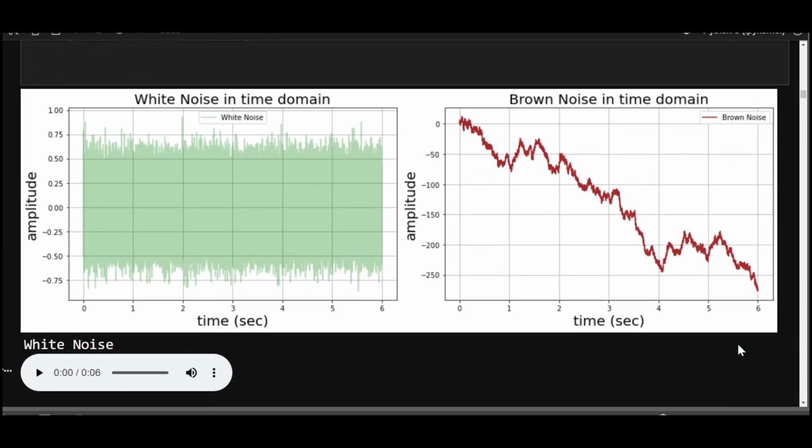So this is exactly how the brown noise looks. This was the white noise, and we just took it and integrated it. So you see here it's fluctuating so randomly. It has some very high frequency components. But when we integrate it, those randomly wild swings of this signal get low pass filtered. And as a result, you see that the signal is now exhibiting very low frequency components. And this is what is called a random walk.